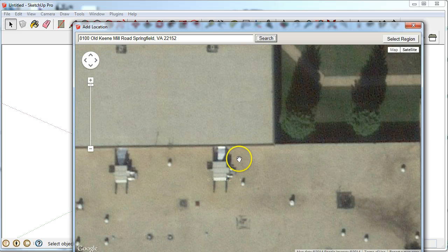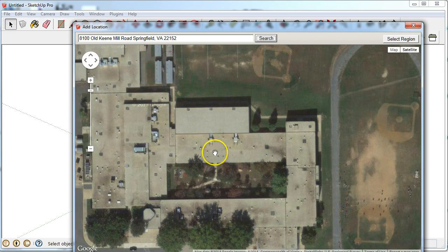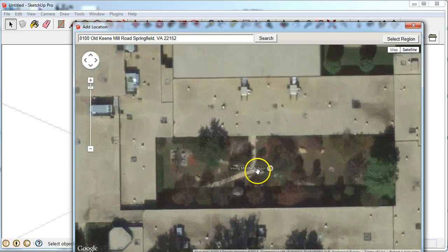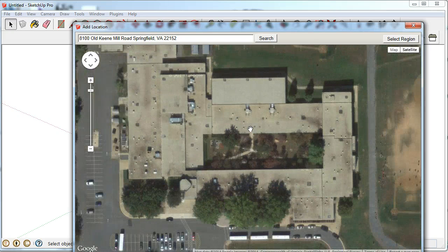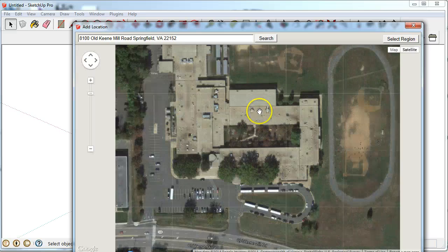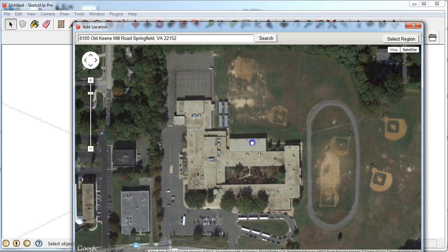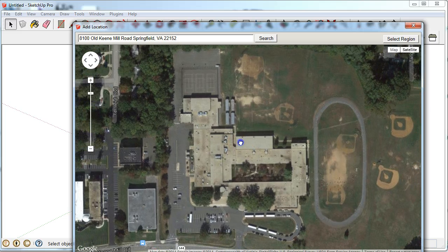As you can tell, here is the location. I already had it open before, but that's okay. This is just to show you that it's going to pinpoint directly to the location of Irving Middle School. I'm going to zoom in and zoom out using the wheel of the mouse, and this looks similar if you're familiar with Google Earth. From here I want to zoom out and pan to wherever I want the image to be using the left mouse button. Hold it down and move.